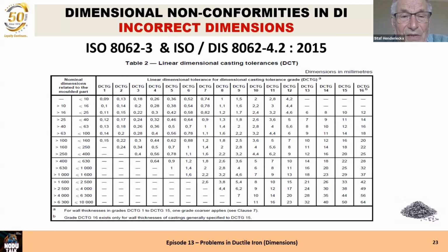It's linear. If you take, for instance, class 7 for the dimensions, then the wall thickness should have class 8, as I told before. Always do that. Wall thickness must have 1 class higher than the class for the dimensions itself. It's also mentioned below the text there in remark A.